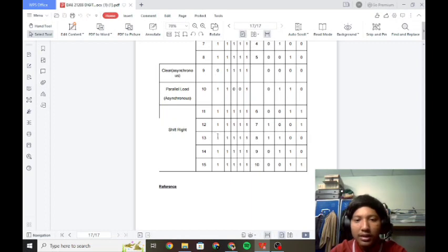At line 13, when clear is 1, input A is 1, B, C, and D also 1. The clock pulse will be turned on the next clock pulse, that is 8. Only A and B output will be 1, and C output and D output will be 0. At line 14, clear 1, input A 1, B 1, C 1, and D 1.